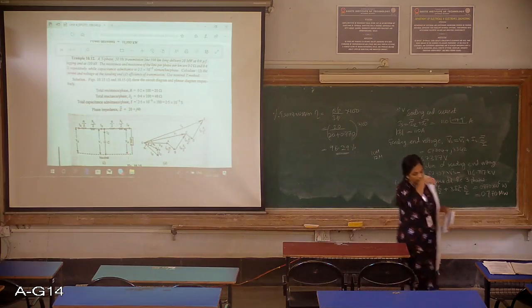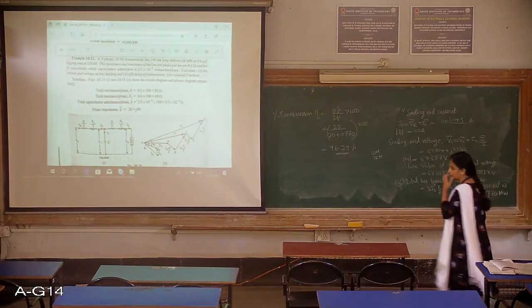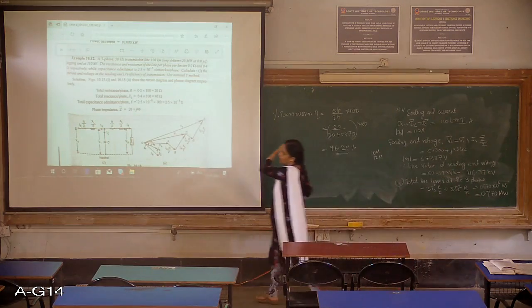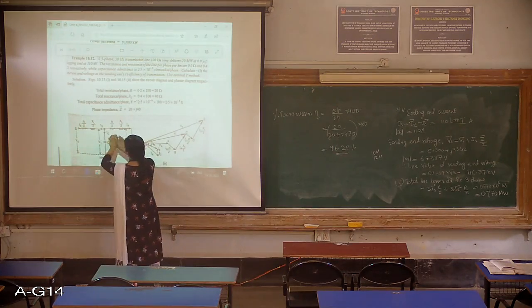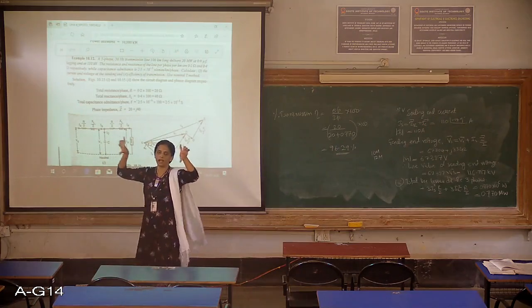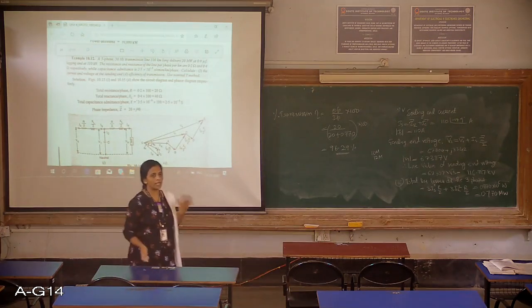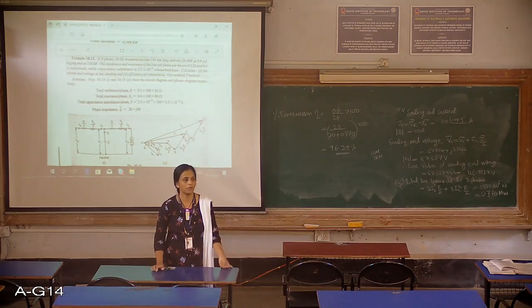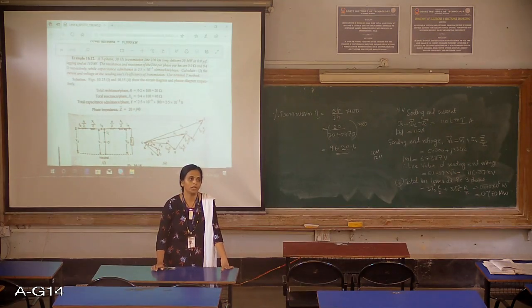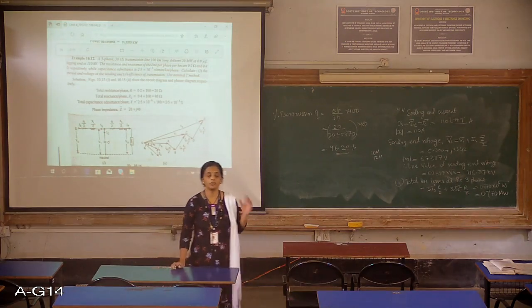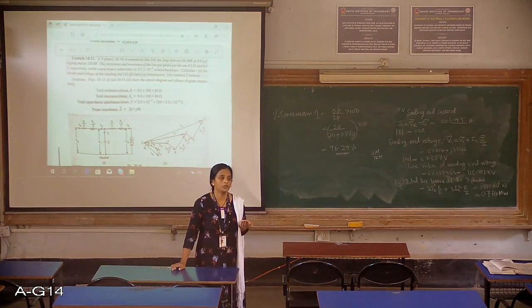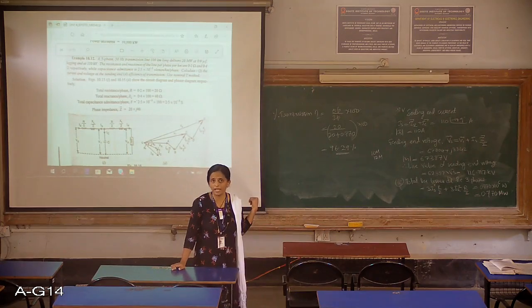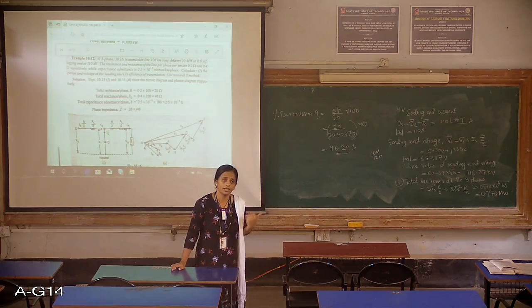Okay, so on similar lines, in tomorrow's class we will discuss the nominal pi method. So in the pi method what happens is, the parameters are lumped at the center and the value of capacitance is assumed to be distributed half each on both the ends. So that concept is very important even with respect to your further semesters in power system analysis, or in computer techniques in power system analysis. You need to know the models very clearly, the nominal T model, the pi model. So later on we are going to generalize these values, okay, they are known as generalized constants or ABCD constants.